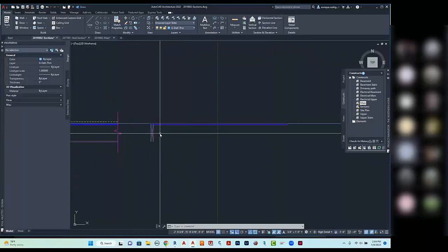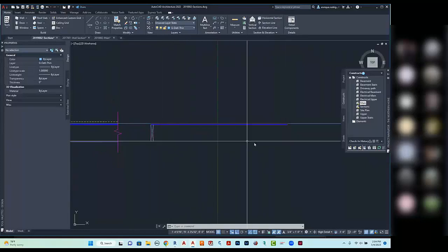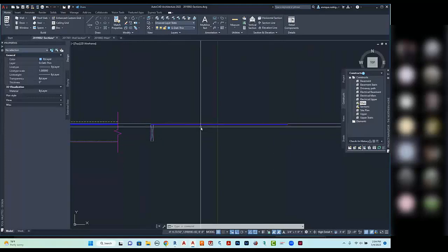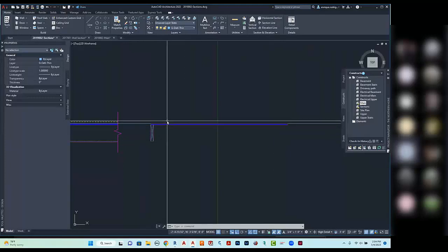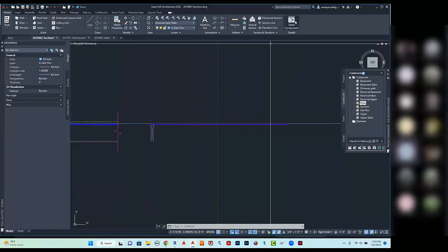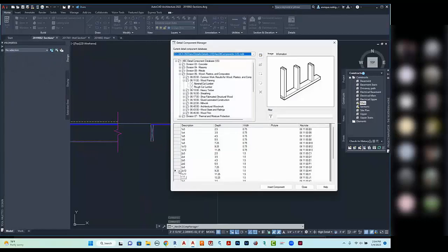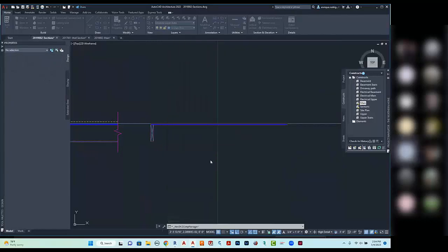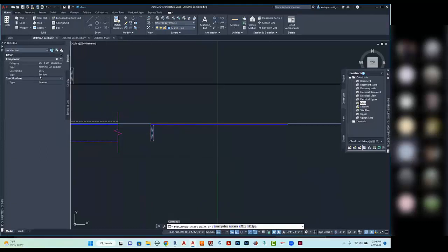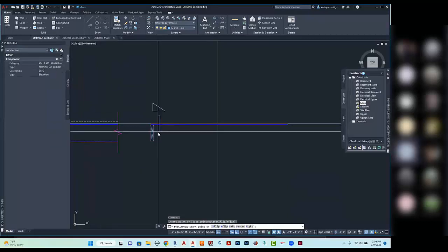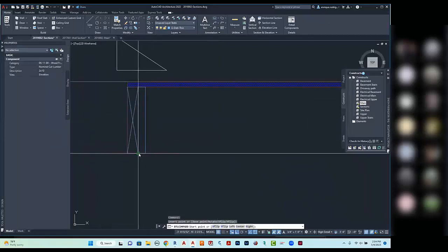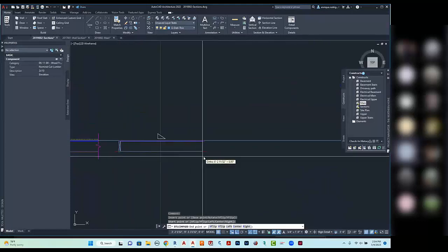That means it's coming at you, and it's being cut by that section cut. But what also happens is we have a number of floor joists which are going left to right, which are actually perpendicular to our view. So we're not cutting through it. We're sort of seeing it as an elevation. So what we can do is, once again, go to the detail components. Repeat the 2x10 insert component at this point. But instead of section here, let's go ahead and left click on that little arrow right there. Let's go to elevation. And we can draw that right there and drag it over to the right.